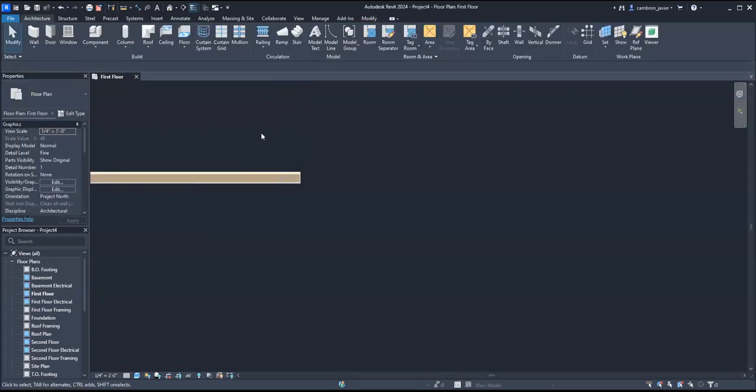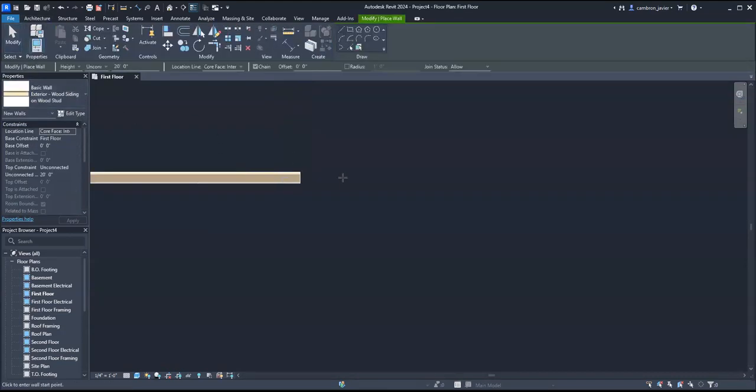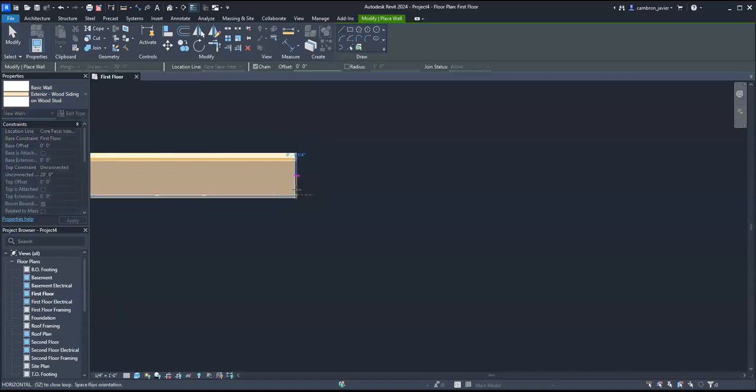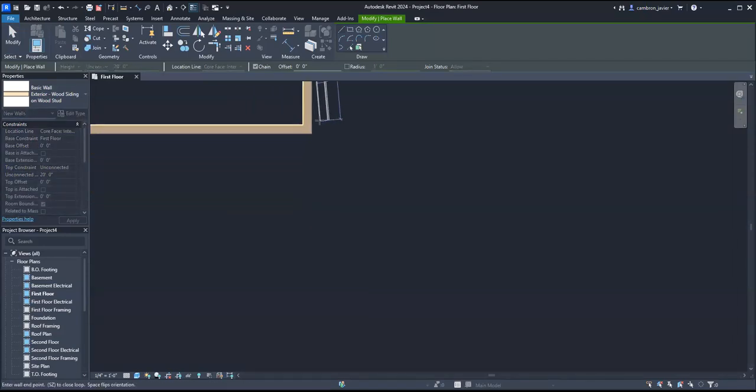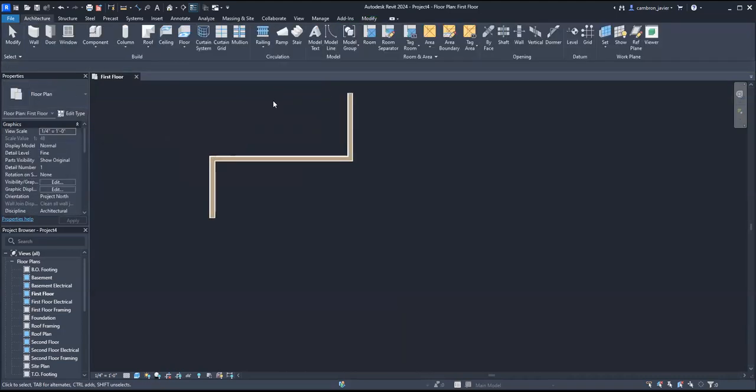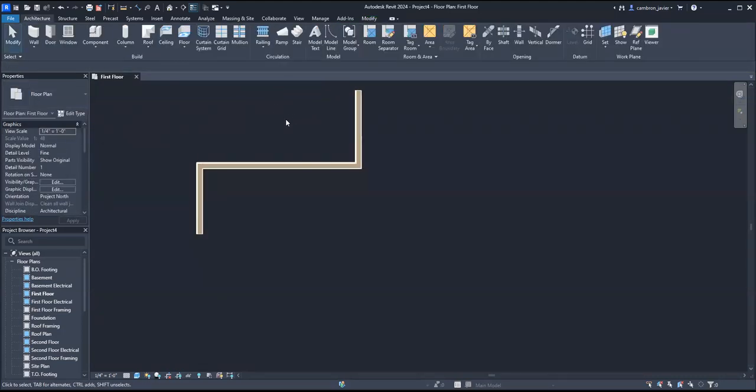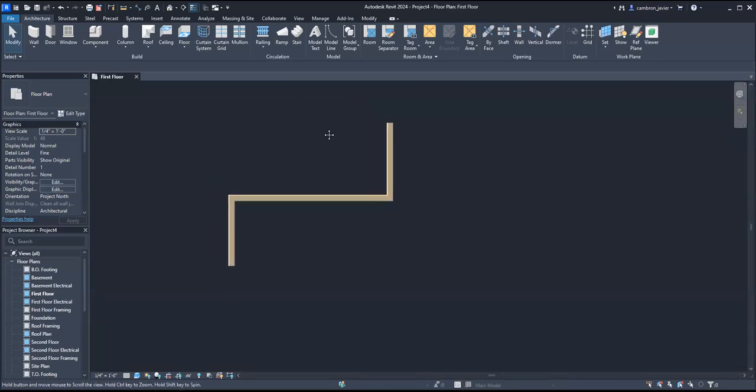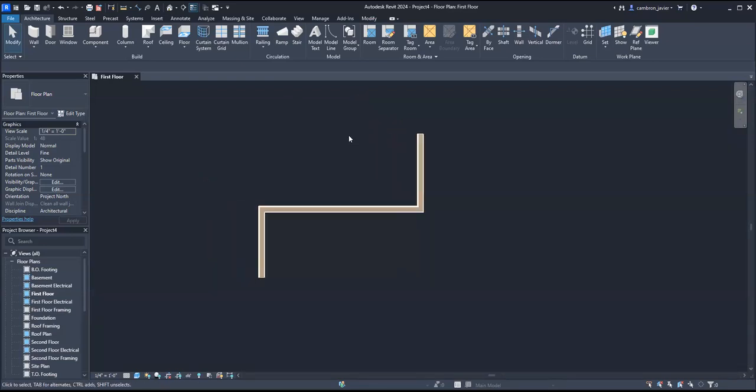I use multiple softwares, so I often forget that we don't have to do that. Especially with the dimensions, so 7 space 5, enter. Okay, hit the escape key. So I have this set of walls, holding down the shift key and then the right key on the mouse. And I've created a set of walls.